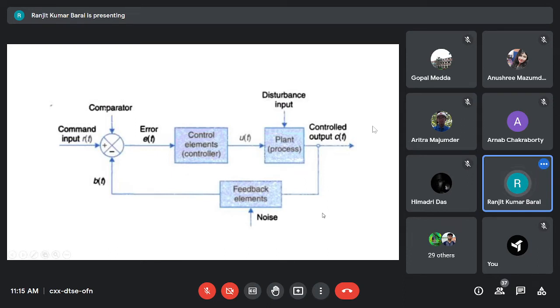If the voltage generated is so weak that you cannot perform A to D conversion, or it does not match the input range of the A to D converter, the input scale, then you have to make some level shifting, some amplification. So all kinds of signal conditioning. All these operations are called signal conditioning. You have to perform signal conditioning. And finally, after all signal conditioning, if the signal is okay, it can be converted to digital, to connect it to a digital display.